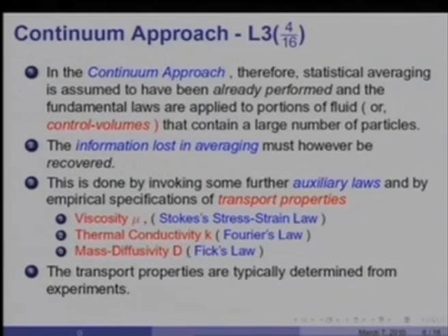You will recall in my first lecture, I said all these are molecular phenomena. Essentially, they are molecular simply because they represent the lost information as a result of averaging at the molecular level. The transport properties mu, K and diffusivity are typically determined from experiments, although theories such as the kinetic theory of gases are available to determine their magnitudes.